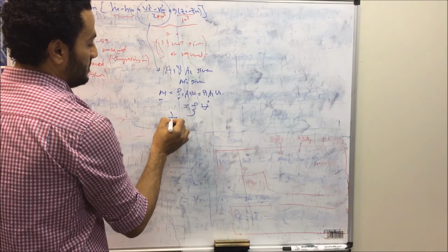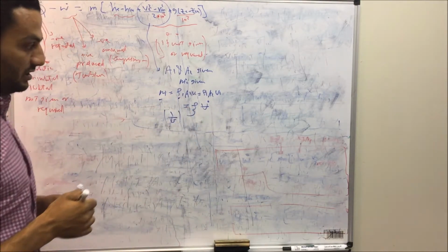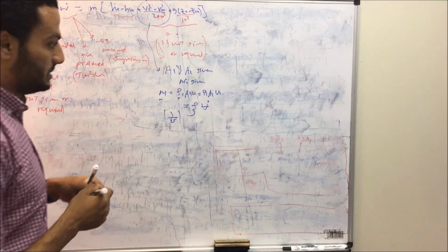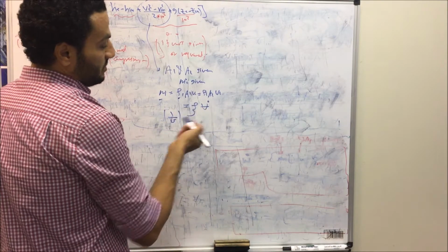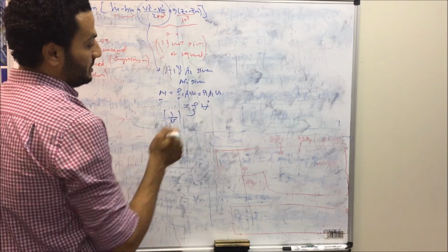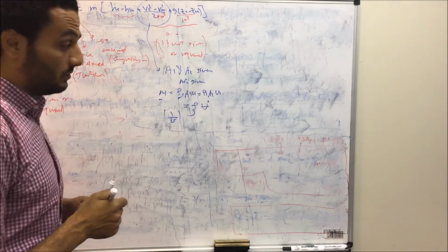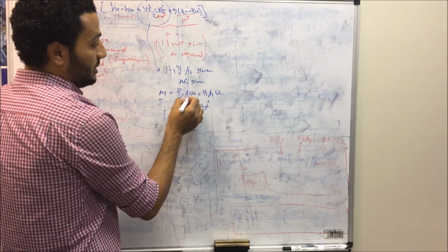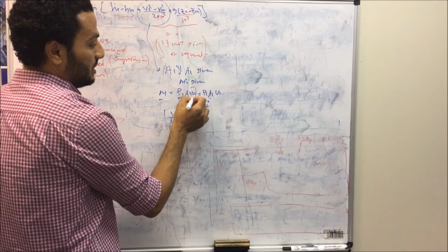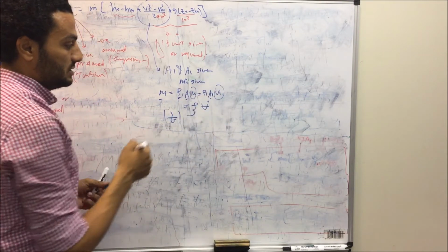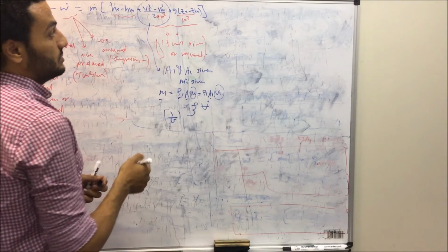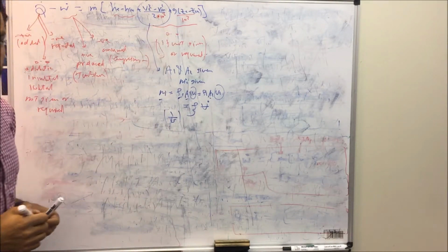Density, as we said, is 1 over the specific volume, which we can get from the table if the working fluid is steam. The volumetric flow rate may be given, then we have the mass flow rate. At condition 1, we can get the density rho 1, which is 1 over the specific volume v1. And we have area 1 and area 2, so we can calculate using the mass equation the velocities V1 and V2, and then we can substitute.